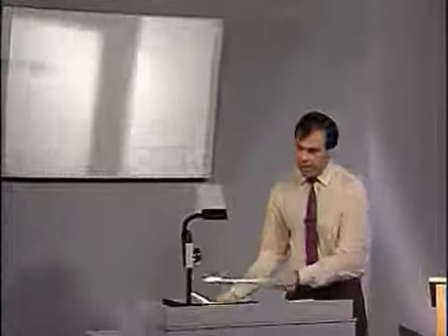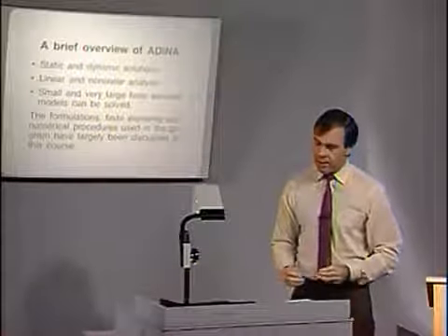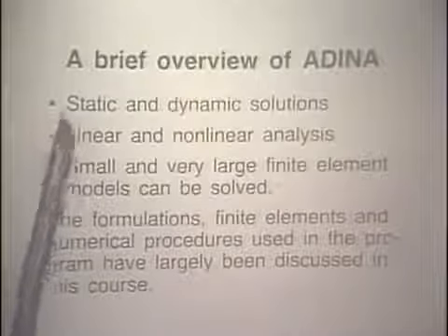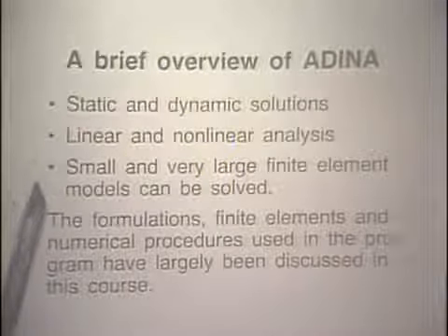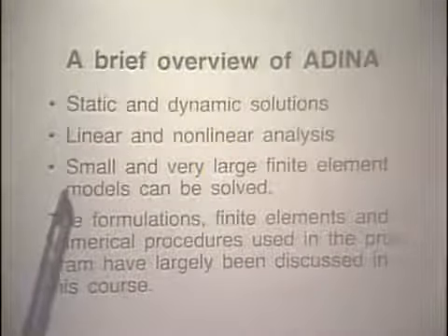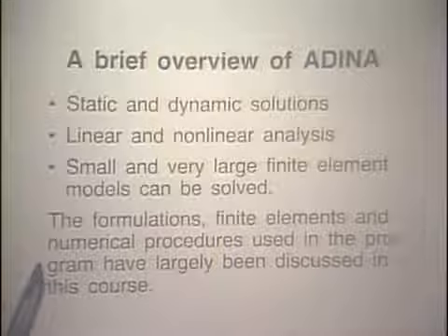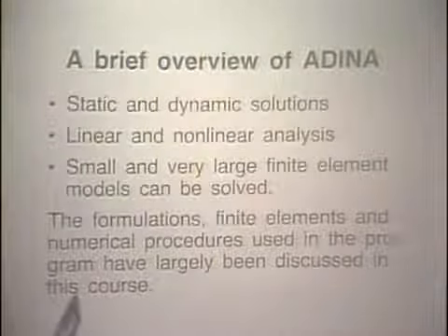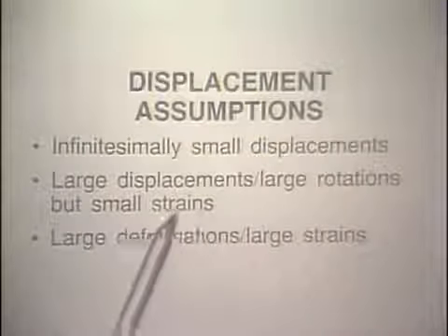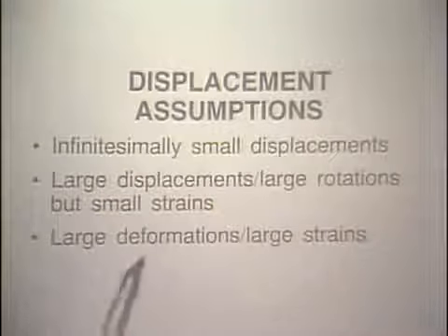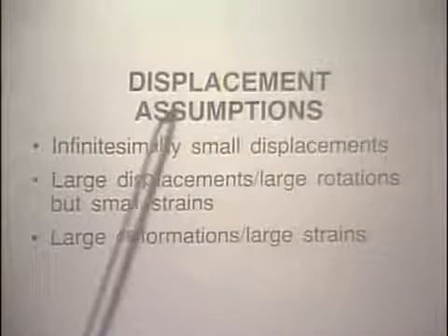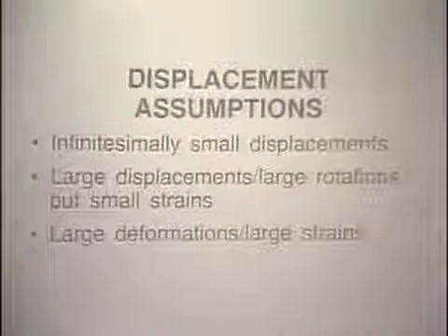Let's look very briefly at an overview of ADINA. The program can be used for static and dynamic solutions, for linear and nonlinear analysis, for small and very large finite element models, and the formulations, finite elements, and numerical procedures used in the program have largely been discussed in this course. The displacement assumptions that can be employed for the finite element models are either infinitesimally small displacements, large rotations but small strains, and large deformations, large strains. We discussed these assumptions, of course, also in the course.